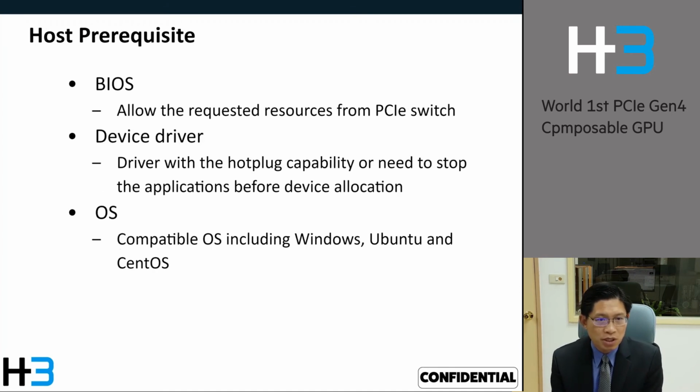PCIe hot plug is fully defined in the PCIe 3.1 specification, then implemented in some hosts. The BIOS of the host should allow the request for resources from the PCIe switch. The device driver should allow the hot plug operations. In GPU hot plug, the GPU operation should be stopped, then do the GPU hot plug. Regarding the compatible OS, let's see the next page.